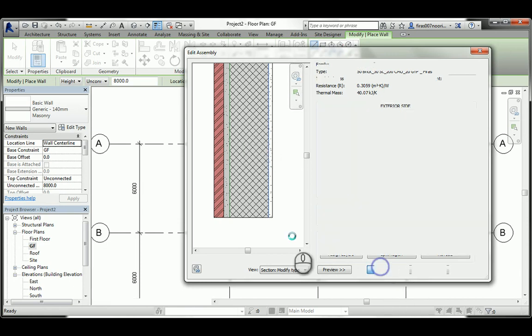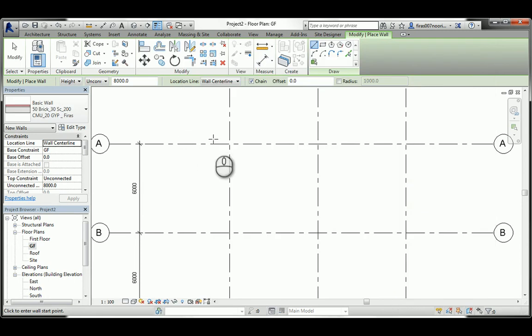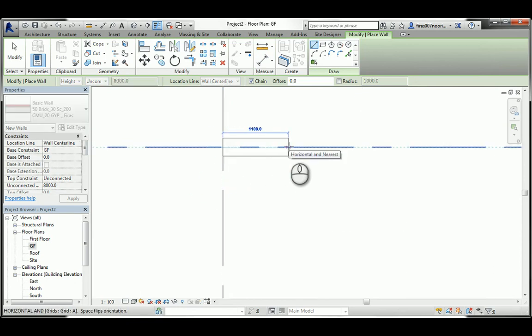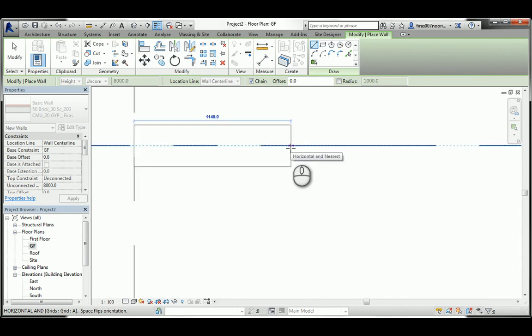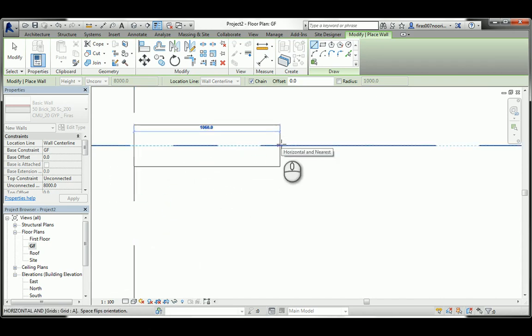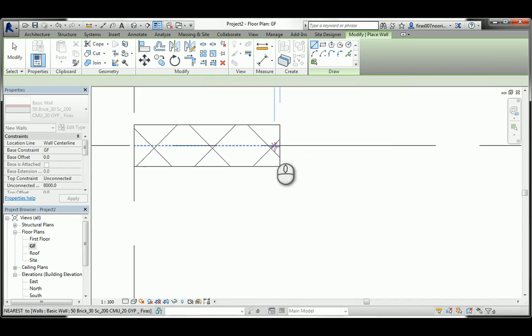Let's have a look at what I'm trying to tell you, in a better way. If I keep this, as we said, as a coarse detail, and I hit here, notice what I'm trying to draw. Now it didn't show any of the details that we spent like 10 minutes designing. It just gave me 2 lines. That happened because I picked this as coarse, so it doesn't care what's inside, just 2 lines for the outside. And see, wall center line is actually the option. So divide the distance from that point to that point by 2 to get the wall center line.